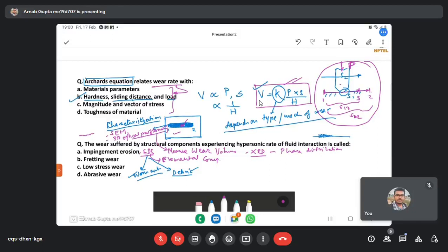And then suppose you are conducting this experiment in a lubricated condition. Suppose you are providing some type of fluid here. So as a result of that, some elements or some molecules from the fluid can interact with the debris and lead to another compound, which can get embedded on this worn out surface. So those things also matter a lot when you are thinking about real life applications.